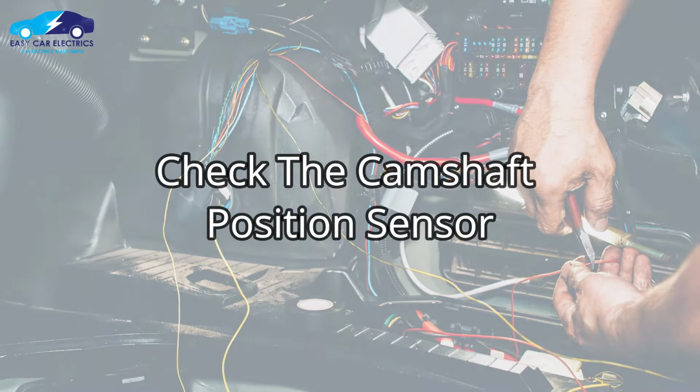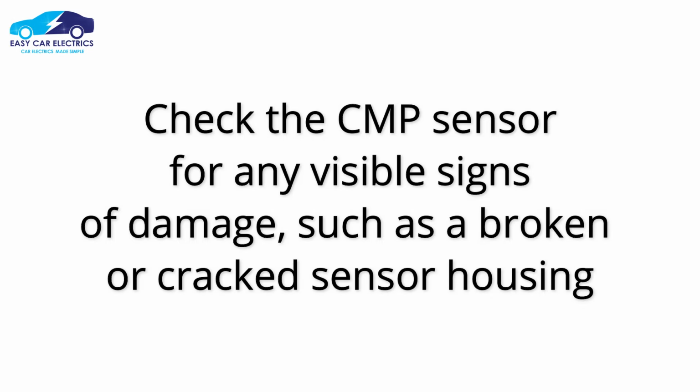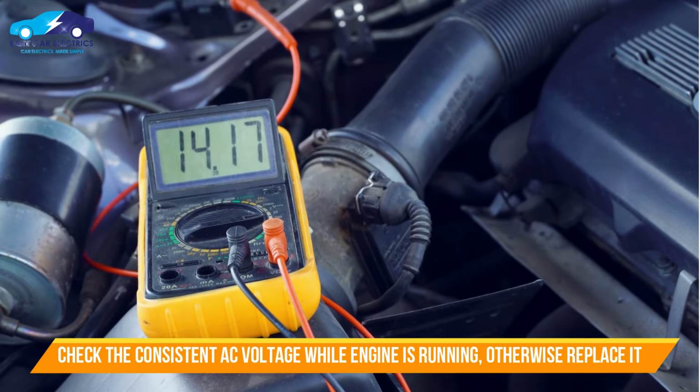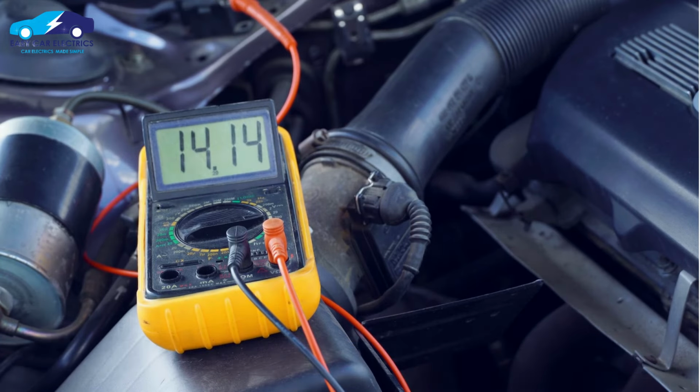Check the camshaft position sensor. Check the camshaft position sensor for any visible signs of damage, such as broken or cracked sensor housing. Use a multimeter to test the sensor's output voltage. The sensor should produce a consistent AC voltage while the engine is running. If the sensor is defective, replace it.